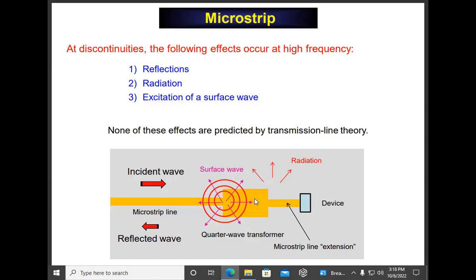Because you said Z0 in a lossy line is a function of the frequency and the material inside the cable, right? Well, okay. Let me see if this is what you're talking about. For a lossless transmission line, of course, Z0 is just the square root of L over C. So it's a perfectly fixed number. It's a real number, and it's perfectly fixed, doesn't change with frequency. Now, for a lossy line, technically speaking, Z0 is a complex number that depends on frequency. We had that in the notes. Then Z0 is the square root of (R plus j omega L) over (G plus j omega C). And it's slightly frequency dependent. That's what's called dispersion, by the way. Okay. In most cases, I think I mentioned this though, in most cases, people don't worry about that.